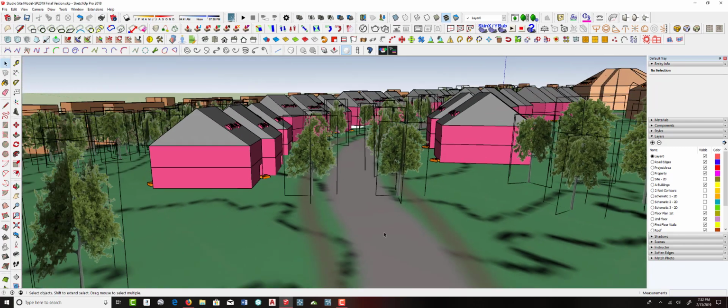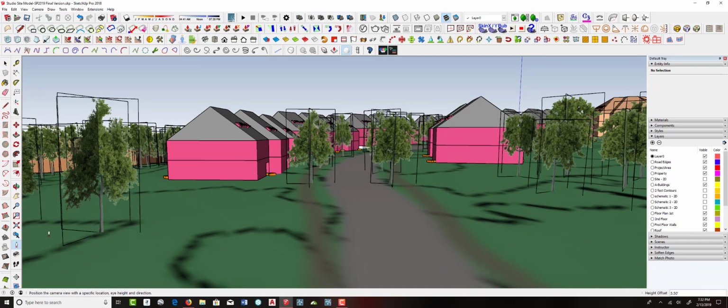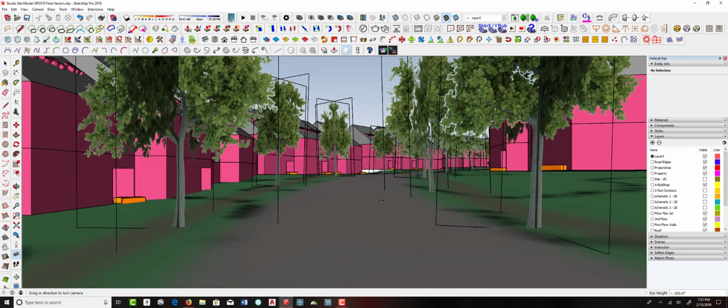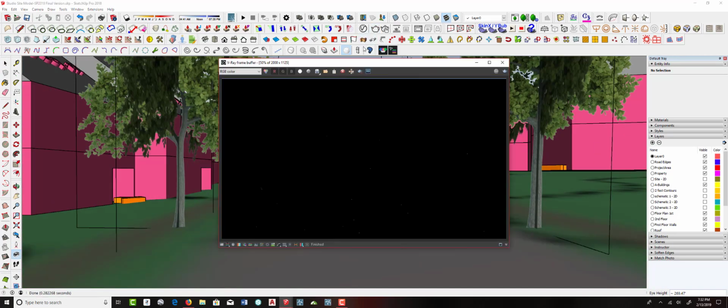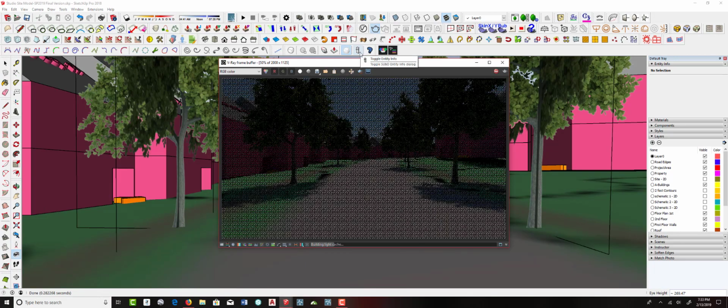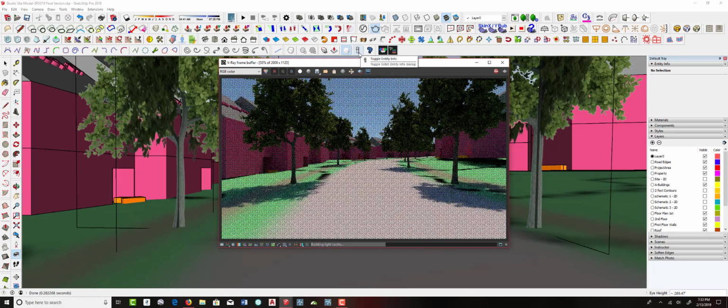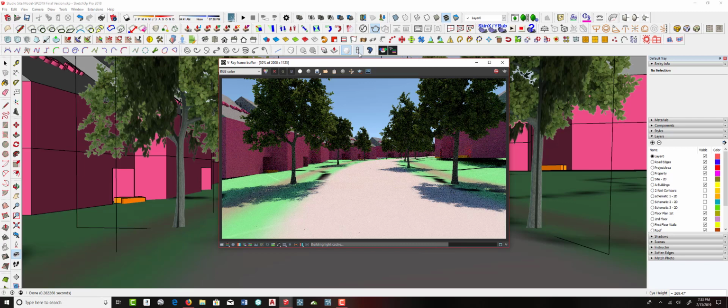So again, if I want to kind of get my view, choose little position view, stand on the road, look through here, do a quick V-Ray rendering. Now I can start really getting a feeling for what does my streetscape look like, what about the spacing, the right-of-way width, the cross-section, do I think this is too big a space? I could start adding things in here. You can see here I haven't regraded this side, so it's kind of floating off the ground.